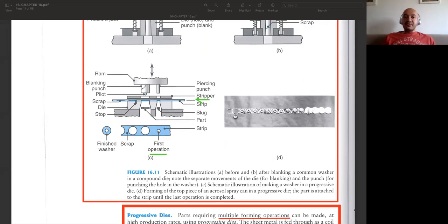Then with the help of this larger punch, we open a larger hole, and this part, this washer bushing, is removed from our strip. In order to increase the accuracy of this punching operation, we have a pilot, and this pilot goes into this hole, and then the larger punch here removes the resulting washer from our strip. So once we feed it continuously, we will obtain our washers in a mass production manner.